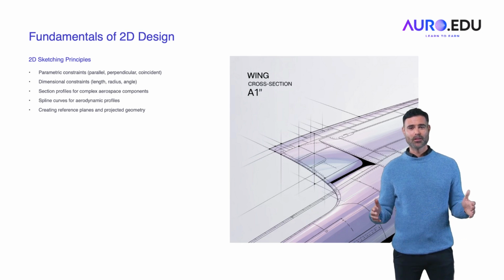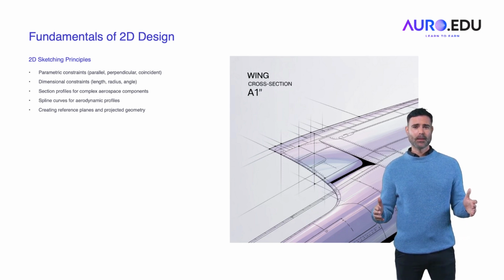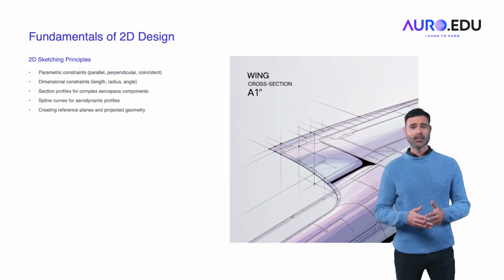Once individual components are modeled, the next step is to integrate them into a complete assembly. Assembly constraints like mate, align, and parallel ensure proper alignment and fitting between parts such as wings, fuselage, and engines. Kinematic studies simulate the movement of control surfaces, landing gear deployment, and other moving parts to ensure that they function as intended. Simulation is key to identifying potential issues in the assembly, such as interference between parts, ensuring that the design works under real-world conditions.